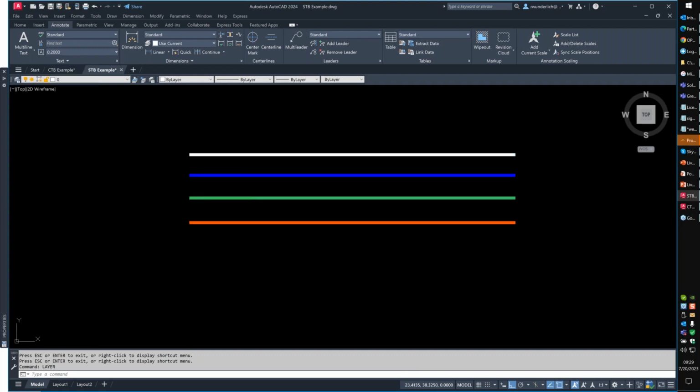Do we have a significant difference between the AutoCAD PDF PC3 and the DWG to PDF PC3? Steve, I'm going to circle back on that. I actually have a blog, I don't think it's been posted yet, where you do get different behaviors when publishing using DWG to PDF versus any of the AutoCAD general documentation, etc. That's because the DWG to PDF is using a slightly older technology driver build, and the AutoCAD PDF with the parentheses, general documentation or whatever is an update, and that one I find works better in most cases.